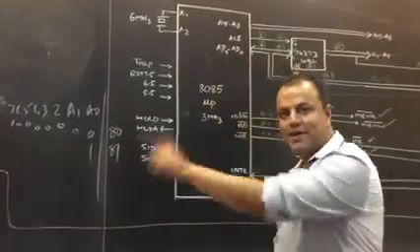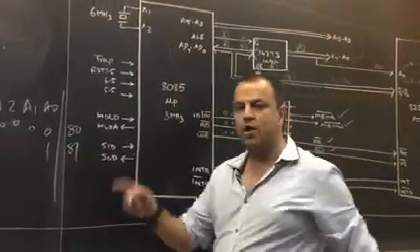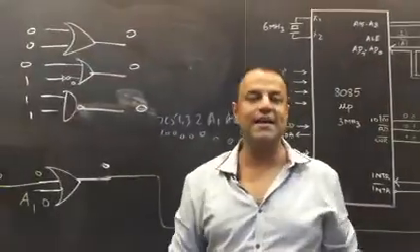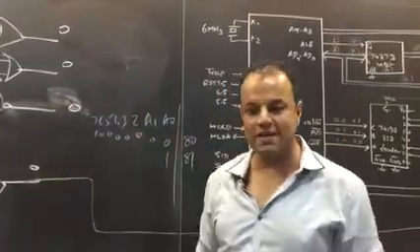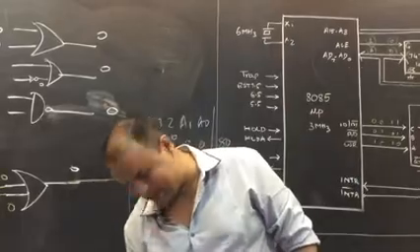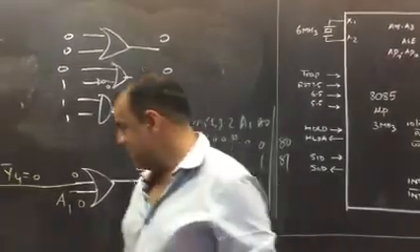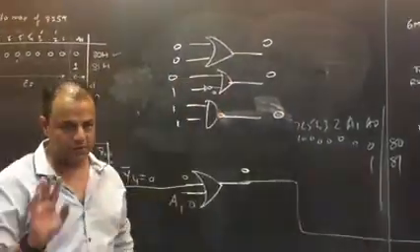Now I am not saying it, the circuit is saying. This circuit is made to select this chip only for addresses 80 and 81. No other address in the world will select this chip. Please tell me, did you understand this? Yes? Good.